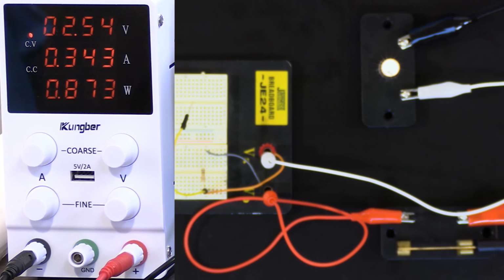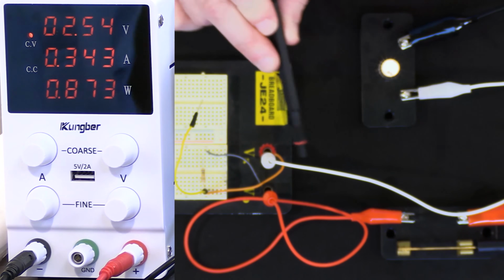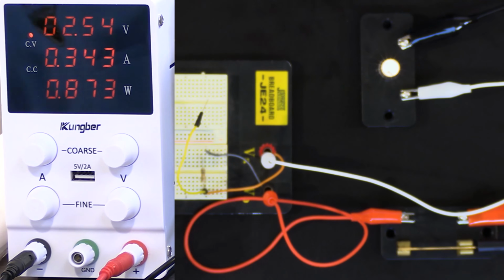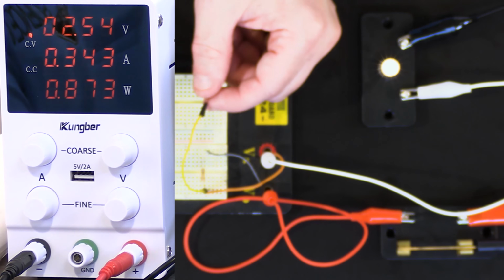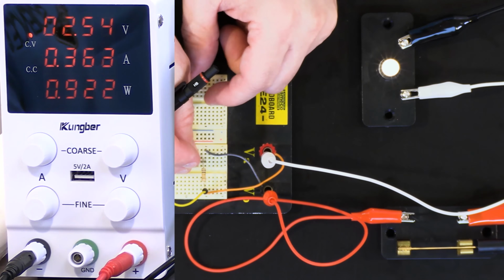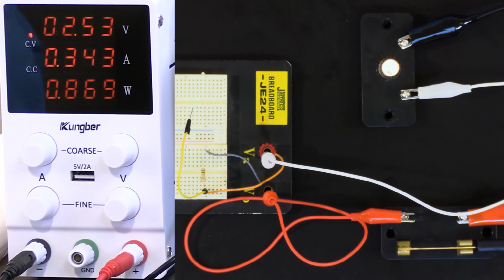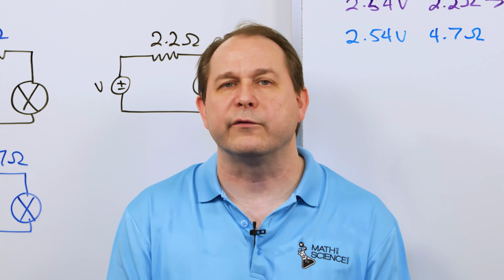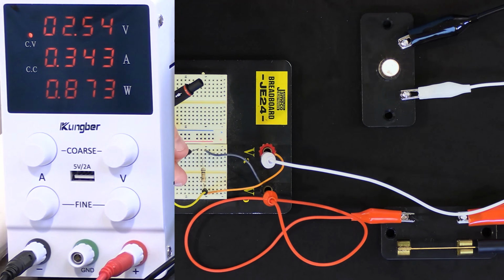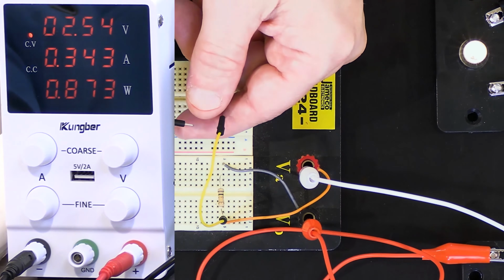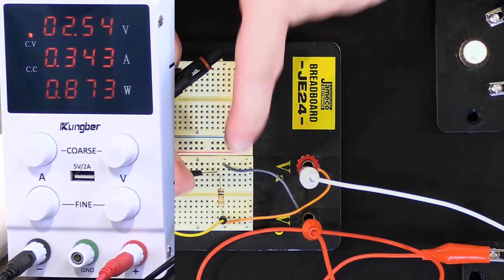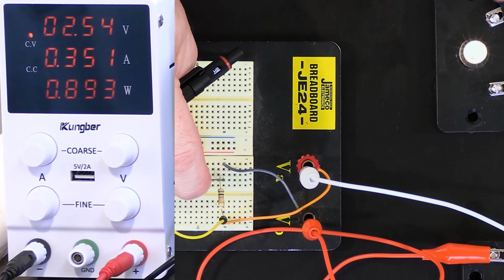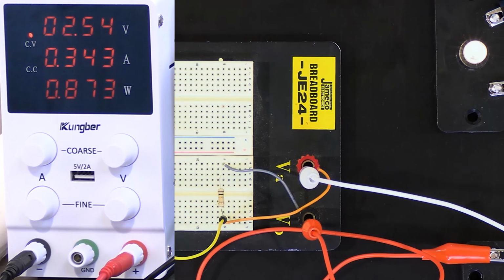That is because the electricity is coming out of the light bulb and going in here, and then it has a choice when it gets to this point. It can go through the resistance, right? Or it can go through zero resistance. Now, I told you the wire is not really zero resistance, but it's very low. So when the electrons get to the junction right here, they don't have a brain, but they always go to the path of least resistance, or predominantly the path of least resistance, which is circumventing or short-circuiting the resistor. And because of that, there's no resistance in the way anymore, and so the brightness of this bulb goes out. Now let me show you why this is dangerous.